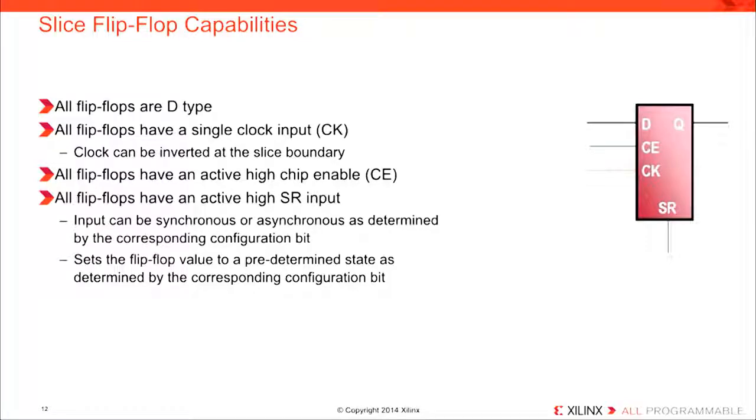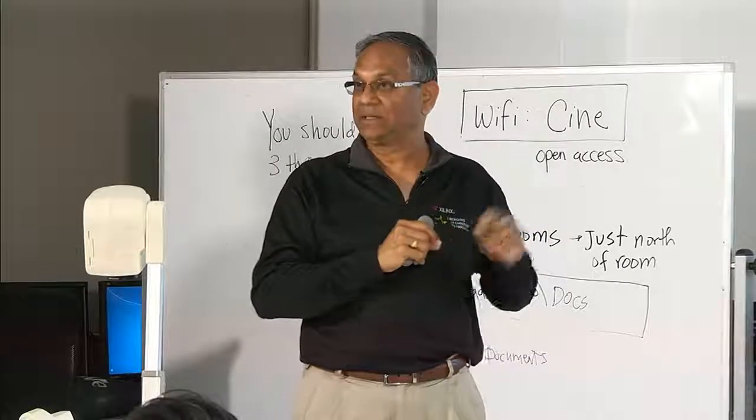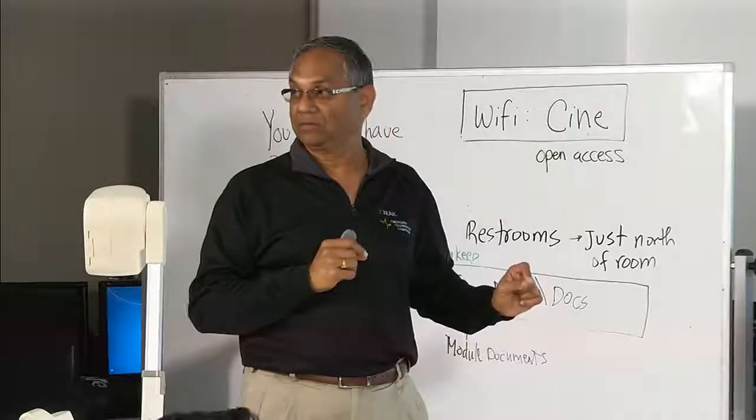There are 8 flip flops. However, all those 8 flip flops use the same clock, right. So, it means if you have 2 different sequential blocks, always block or process block, using different clocks and the rest of the thing is still the same, they will not be placed into one slice, because all the flip flops in the given slice use the same clock, right.